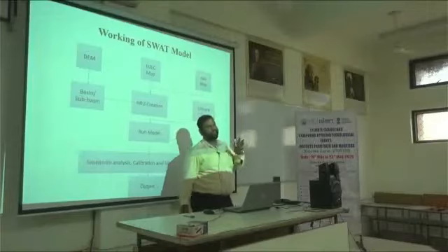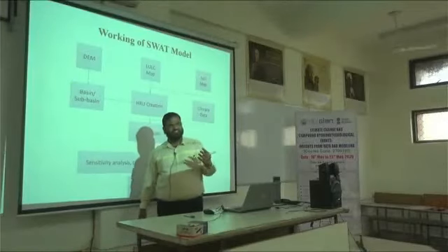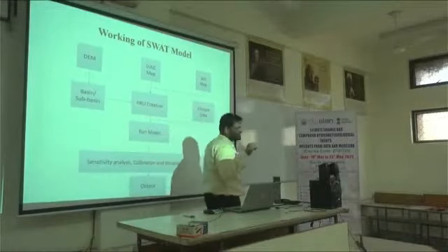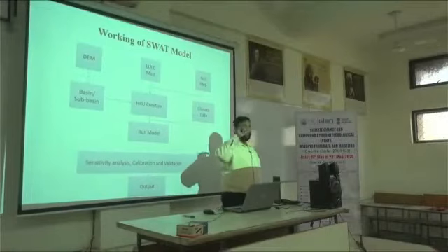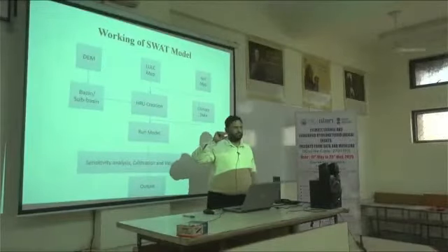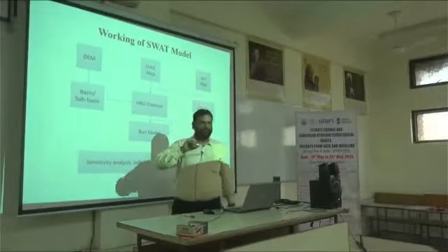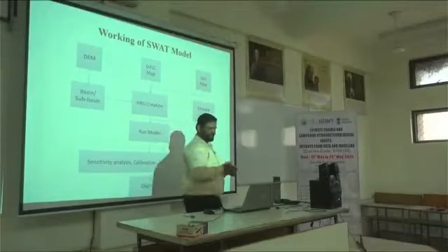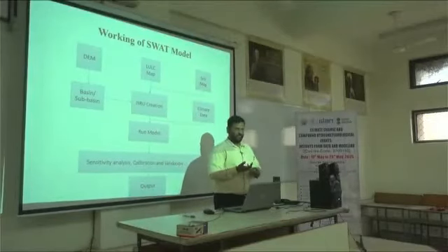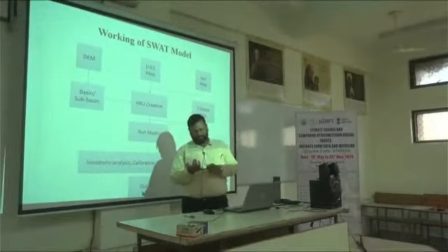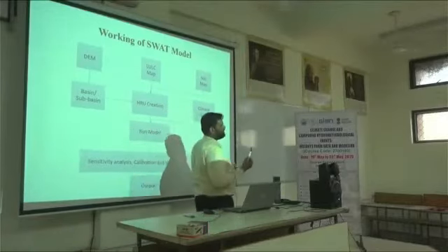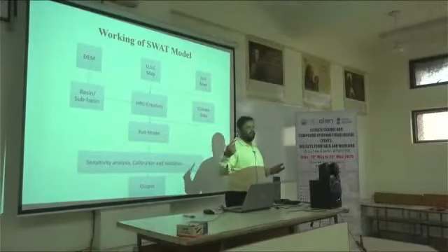They are providing hard copy maps. You have to digitize those maps, and along with the maps you will get some booklets, some manual-type books. From those manuals you have to extract the soil properties, like what soil types there are, what the hydraulic soil group is, how many layers they have incorporated, what the hydraulic conductivity is, and what the anion and cation information is, whatever information is required by the SWAT database.